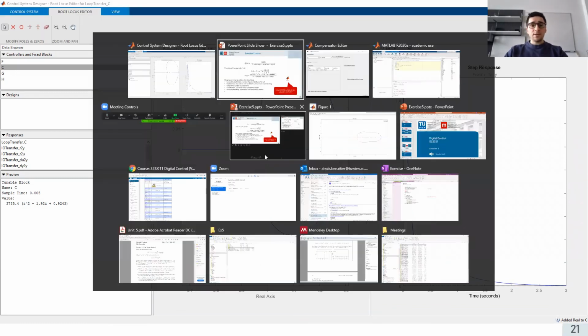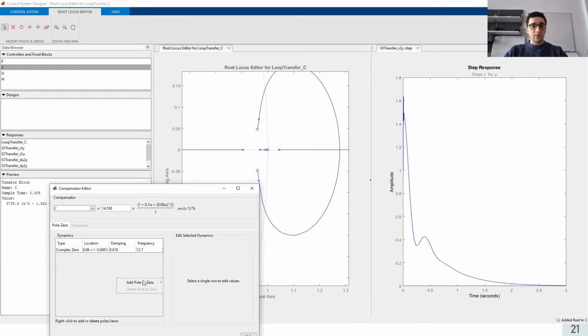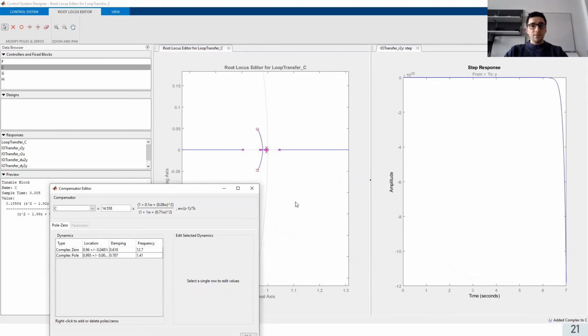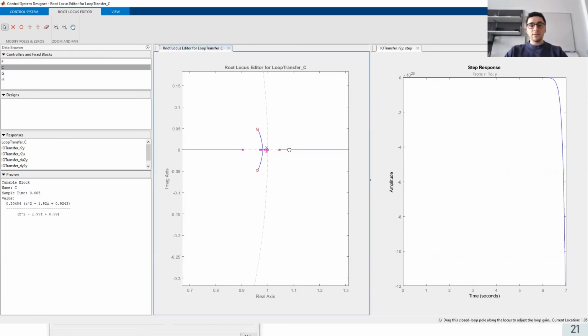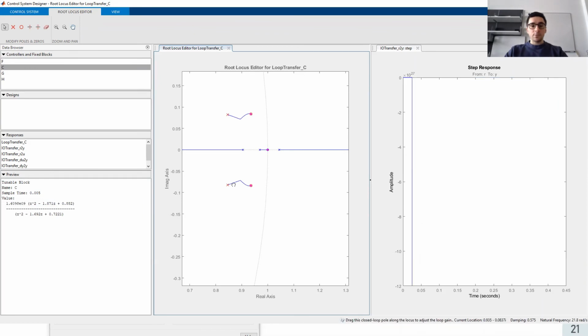And the tricky part is, as I just demonstrated a couple of seconds ago, that if I just add 2 poles, then you see that once again, one of the closed loop zeros here is unstable again. And so you can see that it's not that easy to add some zeros and some poles in a way that the controller is feasible and the closed loop is also stable. So here, adding 2 zeros and 2 poles, probably you can change a little bit the zero location, but I cannot create branching anymore. You see?